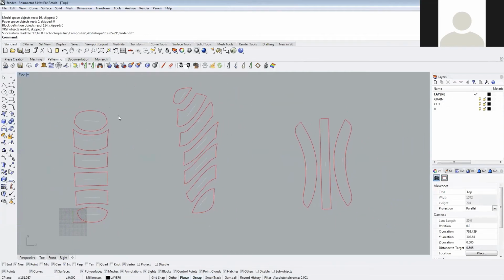And there we go. We can see that we've got our cut file here. The important thing that we're looking at is every single piece has a cut line, and it also has a grain line depending on the edge that we selected. All these pieces, the grain lines are all left to right horizontal. For these pieces over here, the grain lines are all at a 45-degree angle, or on the bias. And for these pieces over here, the grain lines are all perfectly vertical.